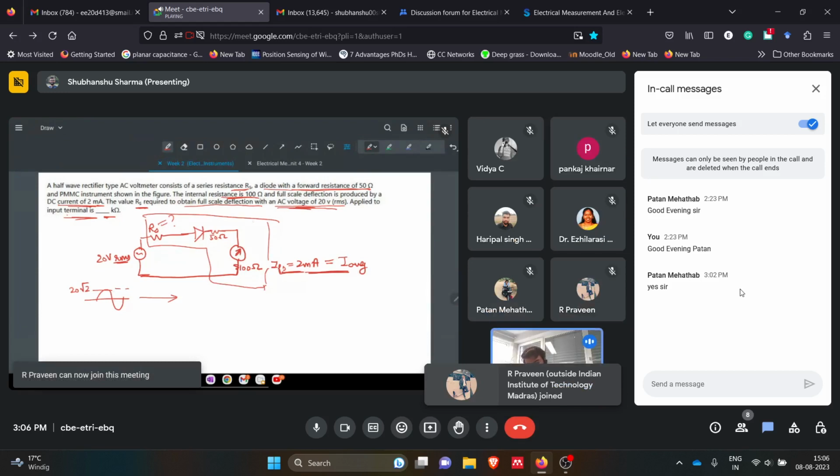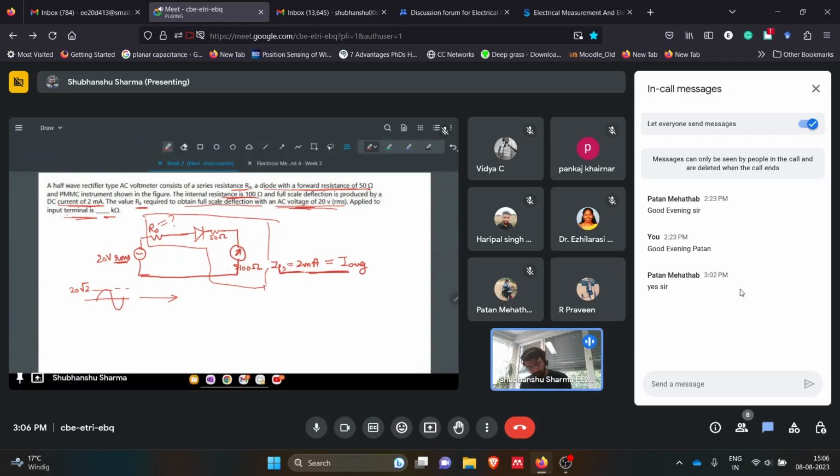So this signal we have fed to this meter, and then let's go step by step. What this diode is doing is basically making this signal a half wave rectified signal. For the positive cycle it will allow the signal, for the negative it will not. Another thing is being done in the meter itself, so this is all being done in the meter.